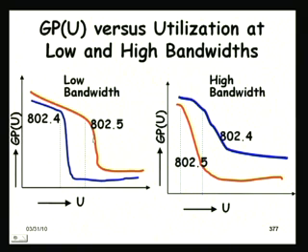And this sharp drop actually indicates the absolute breakdown utilization value. So, we were saying that at a certain utilization, suddenly the message set will start missing the deadline. So, the sharp drop here indicates the absolute breakdown utilization from this point onwards. This is the ABU for this one, this is the ABU for this one. This similar thing we had seen on the ABU plot. Now, for a high bandwidth, the situation is just reversed. The 802.4 is performing better from the beginning and keeps on performing better.